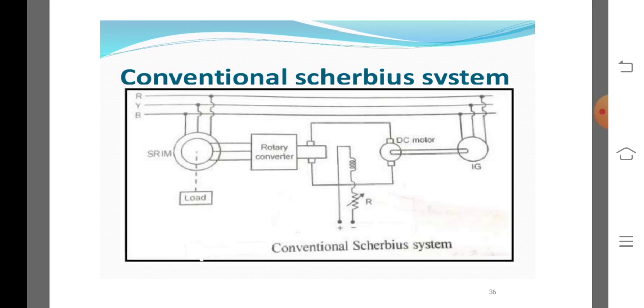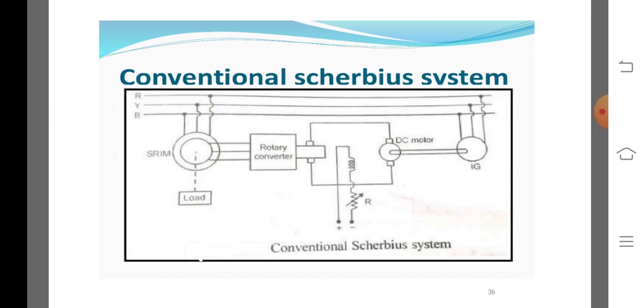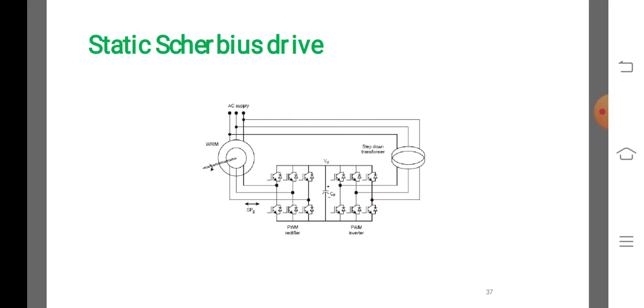It is very expensive and has control complexity, but it has some advantages: a near sinusoidal rotor current that gives reduced harmonic loss, and a machine overexcitation capability that permits leading power factor operation on the stator side. In fact, the cycloconverter's input lagging power factor can be cancelled by the machine's leading power factor, so that the line power factor can be unity or leading.